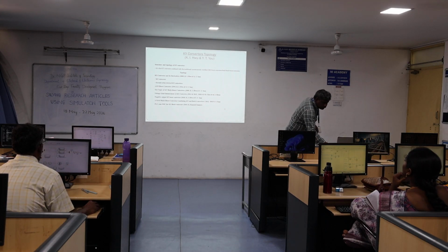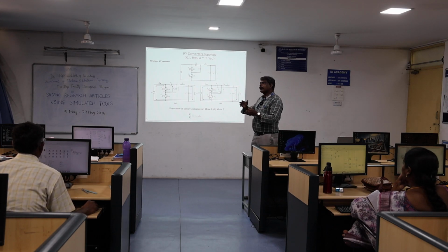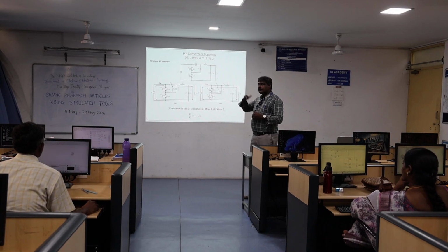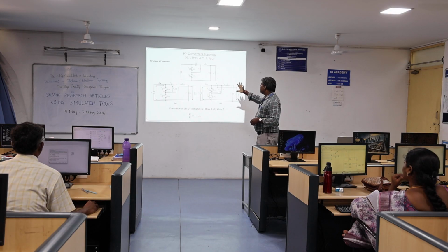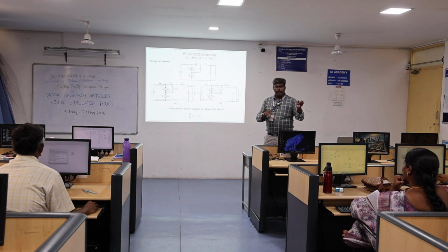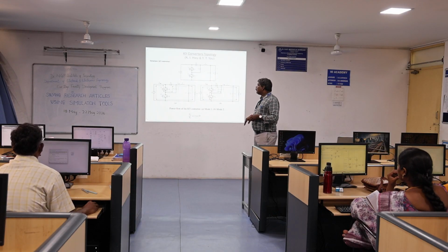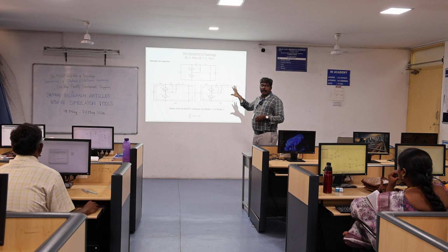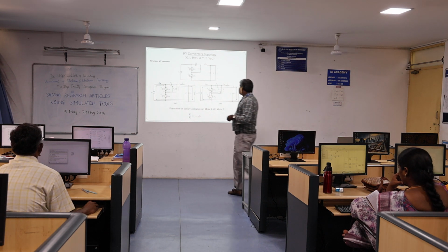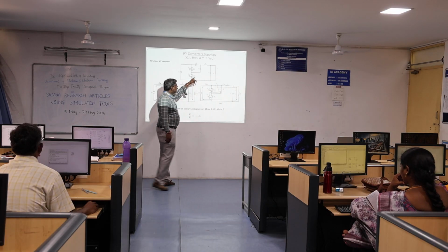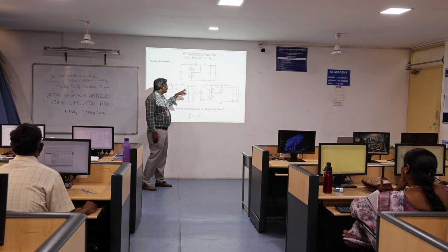So moving on, this is the structure. I already told how to form the KY buck-boost converter and KY boost converter. Initially we need the KY converter structure. I hope all of you know the boost converter structure and buck converter structure. Coming to the KY converter, there is a fundamental basic circuit for the KY structure. It consists of two switches, one diode and three storage elements, L and C.